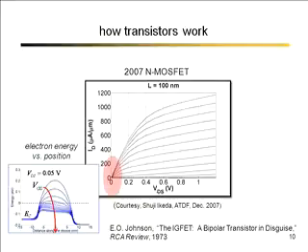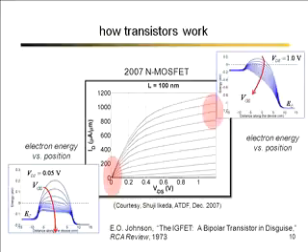So that's one regime of operation. Now, if you look at high drain voltage, all we've done now is to lower the energy in the drain. We've applied a significant voltage, about a volt or 1.2 volts. We've lowered the energy in the conduction band in the drain by a significant amount. There's a Fermi level in the source. Now there's a different Fermi level in the drain that's way down here, 1 volt lower.